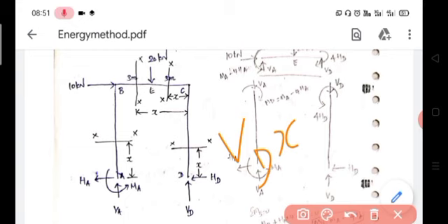The second force is the HD force, a horizontal force. It creates a hogging moment about section XX. Since it is a horizontal force, the perpendicular distance is the vertical distance, which is the height of the column, 4 meter. Therefore minus 4 into HD.